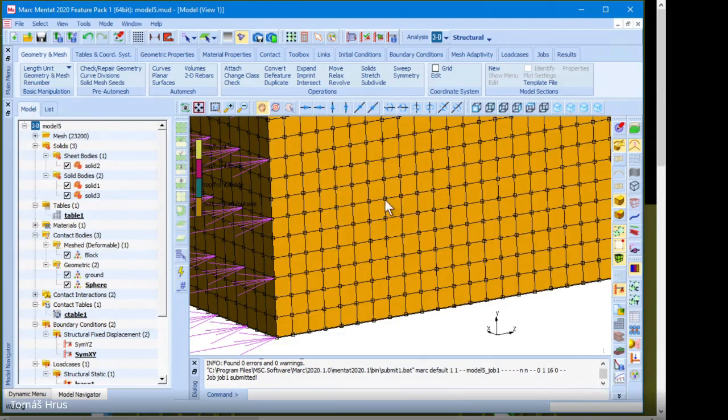Great. And using the sweep, you can see the help. If there are duplicated geometric or mesh entities, the sweep will just remove the duplicities. So using the subdivide, it's important to use the sweep then.